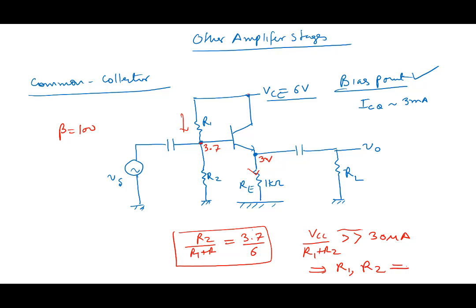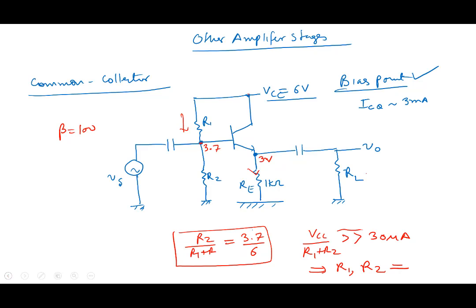Okay, so this is our amplifier. For the sake of argument, let's take RL equal to also 1K, for some values here. Anyway, it is biased at ICQ equal to 3 milliamperes, and VCEQ is biased at 3 volt. That's what we have biased it.